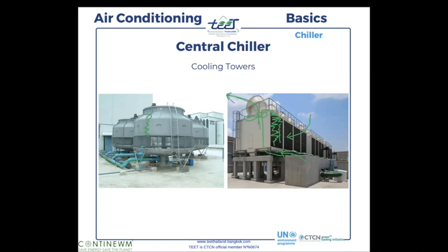And you have exactly the same on the other side, it just looks different. The water is supplied at the top in fine droplets all around. You have the air, and here you have a big fan. The air passes through the water droplets, cools them, and is extracted here. The water is then taken back to a different circuit when it's cooler. So the water is dropping on the side, getting cooled by the outside air.